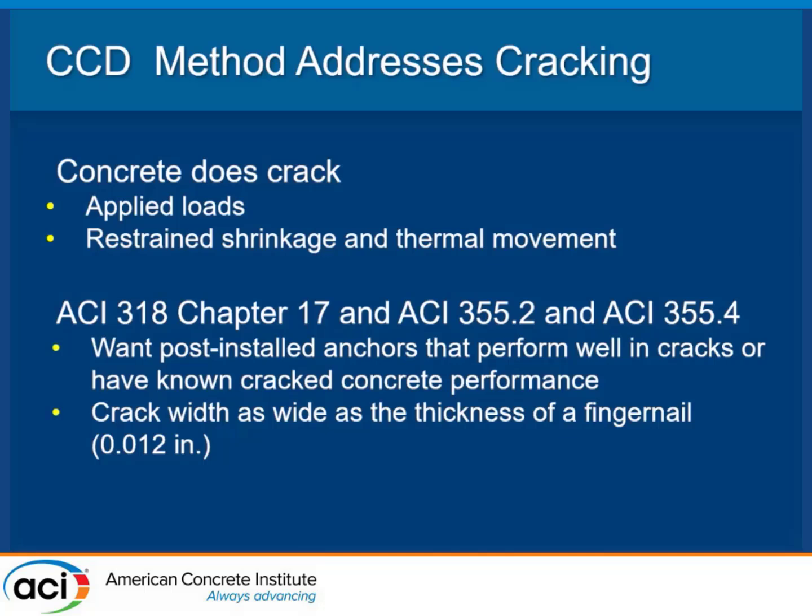Okay, so concrete does crack, right? So we want to address that. We do require that in 355.2 and 355.4, that we do make them test with a crack, and that crack width is 0.012 inches, basically the thickness of your fingernail. So if you're out there walking along, you're seeing cracking, and you put your fingernail in there, and it's much larger than your fingernail, you probably aren't meeting the capacity that you designed for. Okay, but they are good up to that thickness or width of crack.